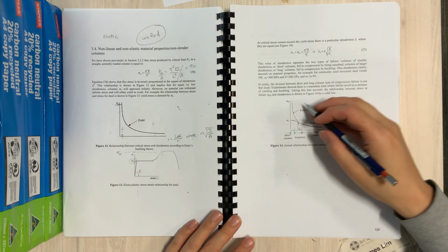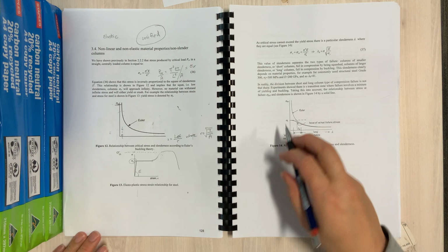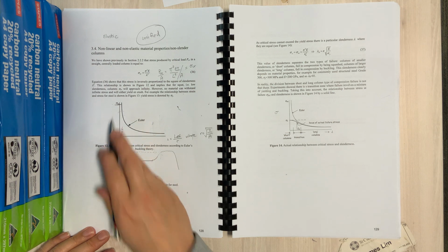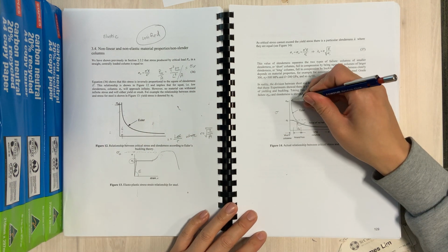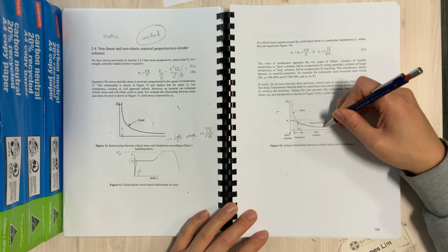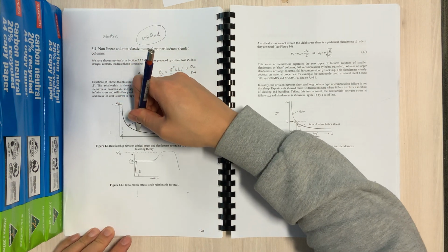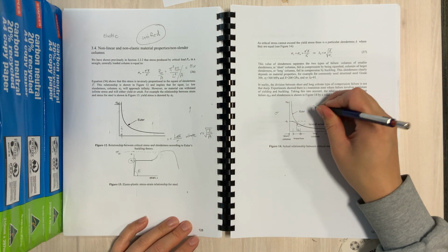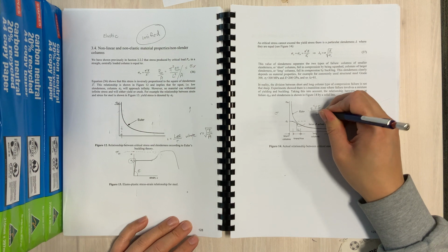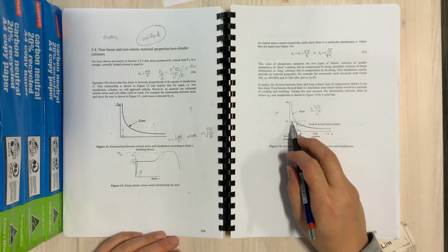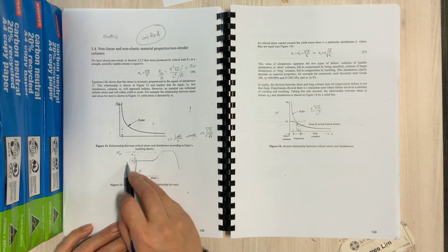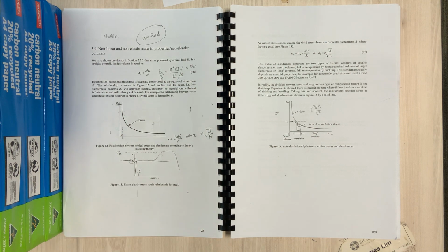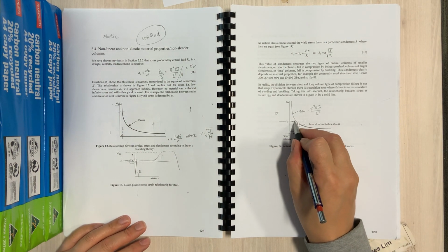So here is the whole thing unified. This axis here would be the stress, and this would be the Euler, so that would be down there. That would be your Euler, representing your pi squared EI over L squared. And then this portion here, we've got the yield stress, which we've measured from the coupon, so that may be 300. Let's just say it's a number, and then here we might just like to draw a line there.